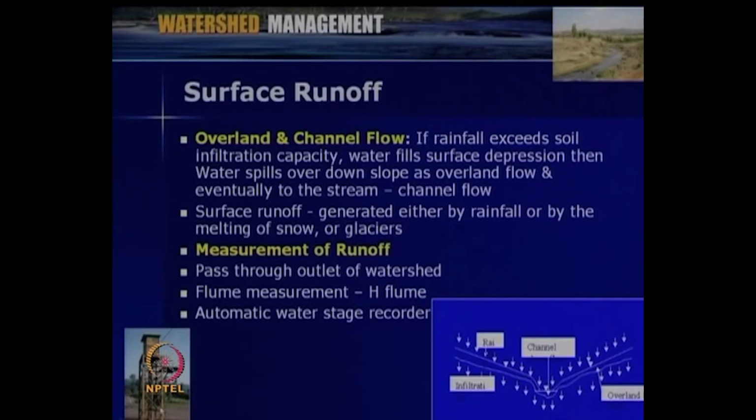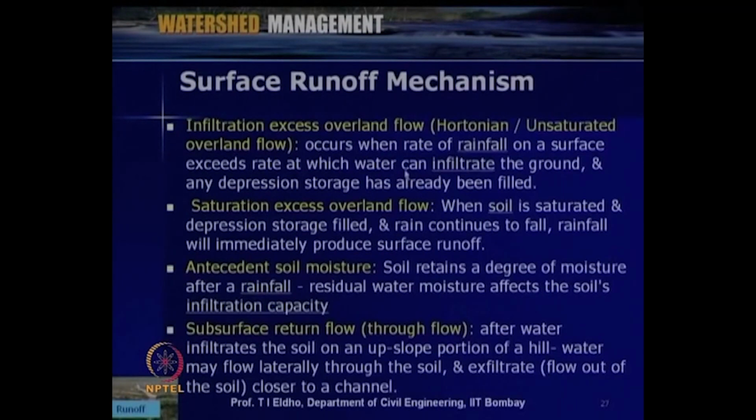We can measure the runoff in a channel using, for example, an H flume or various automatic water stage recorders, to measure what is happening at the outlet of a watershed or at a particular location of the stream or river.